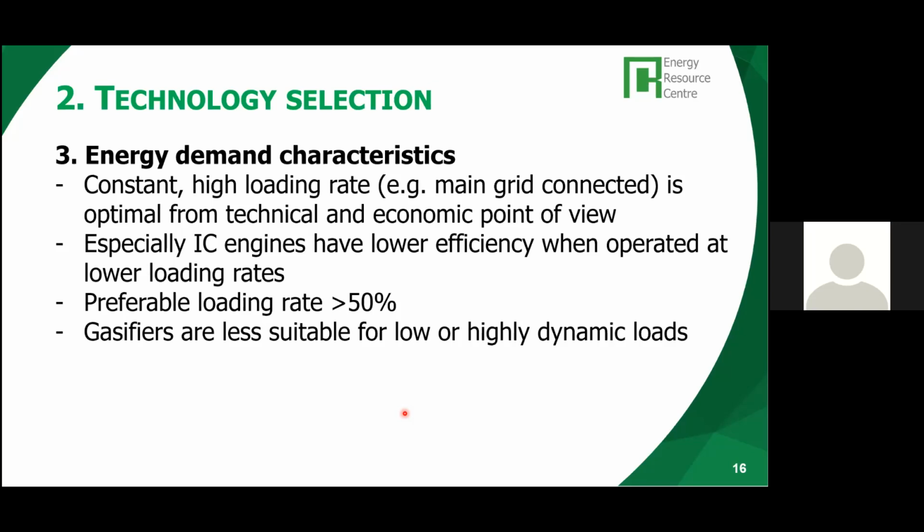In general, for most of the systems, you can say that a loading rate of at least 50% should be strived for. That's both for engines, but also for turbines, for example. And what is important to know is that the gasifiers are not so very suitable for very low loads, so less than roughly 30% usually, or highly dynamic loads for very large load fluctuations.